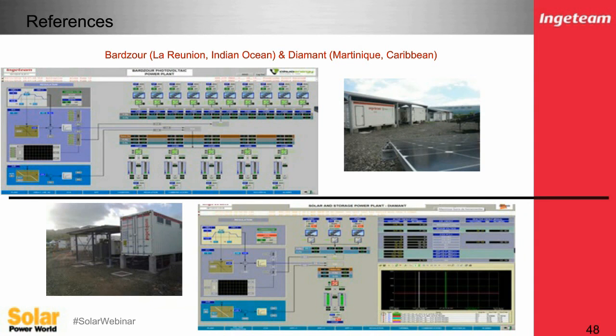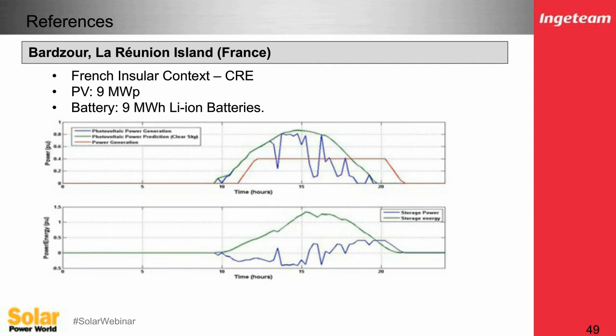This one utilized our SCADA system as well, where the grid operator has access into the plant. He or she has the capability to see the operating conditions, and access frequency regulation for grid support applications of the plant through our SCADA. And here is actual data taken from an installation in a real live recording through the data logger of the plant. This one again is the PV firming application.